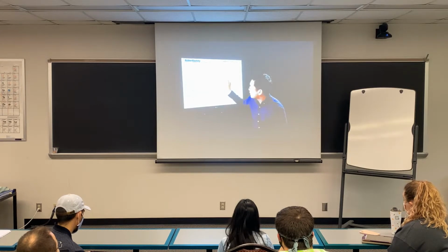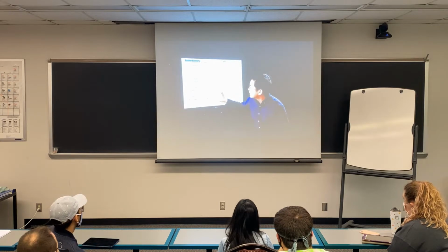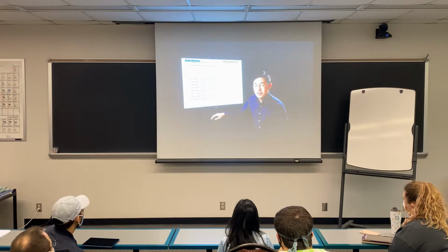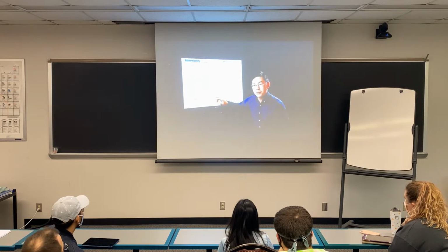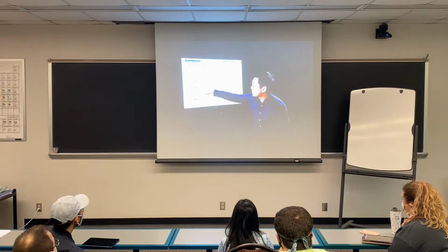And this has been discussed quite nicely, right? So Gaussian coil deformation distribution, we talked about it, and it likely needs a fix because it's not going to work out. Chain conformation before the deformation is the same as chain conformation on crosslink states. So this is going to be related to another theory, how we can address the conformation change before and after. This is also important because if the crosslink influences the morphology, then it will impact our theory. But most of the time, it's not a big effect, not as big as assumption 3.